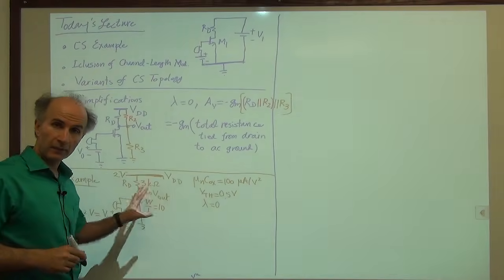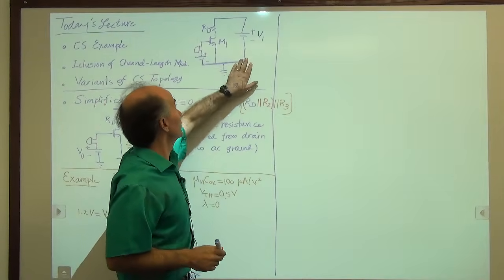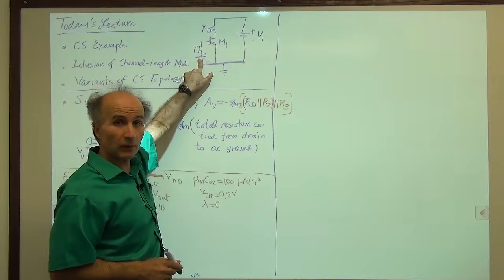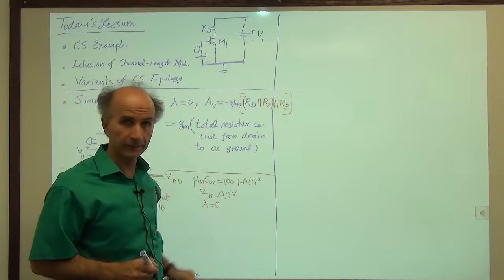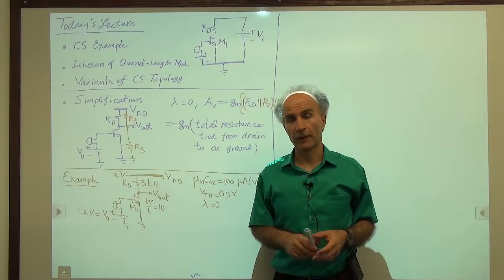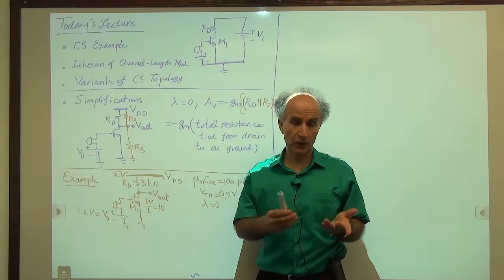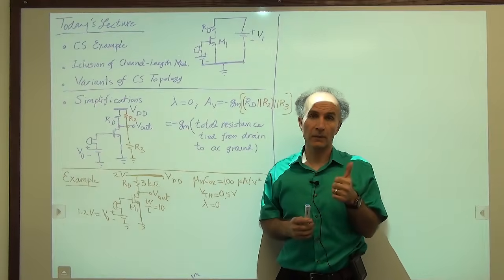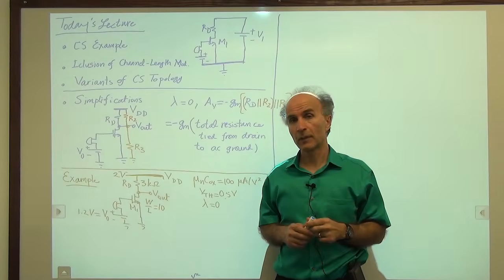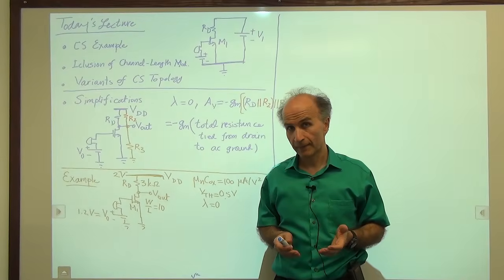So anytime this picture is not quite clear, you go back here. You remember that this is 2 volts from here to here. This is 1.2 volts. That's 3 kilo ohms, etc. All right, we would like to analyze this amplifier. And if you remember from the procedure from last time, analysis or design, the first task that we have to embark upon is to calculate the bias conditions.